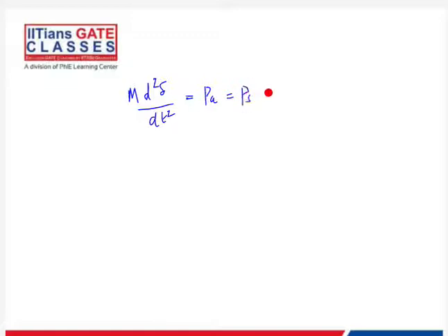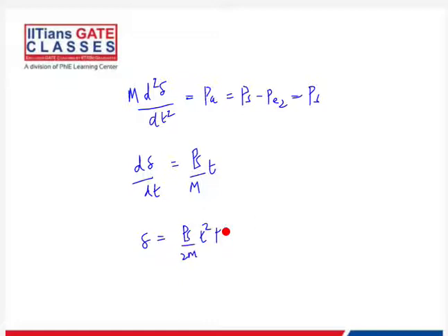So we are going to assume that the electrical output is completely zero. That's the solid short circuit fault, right? Just for the sake of the derivation. So if we integrate it, ∂δ/∂t will be Ps divided by m e. We integrate it again, we will get δ as Ps by 2m t square plus a.